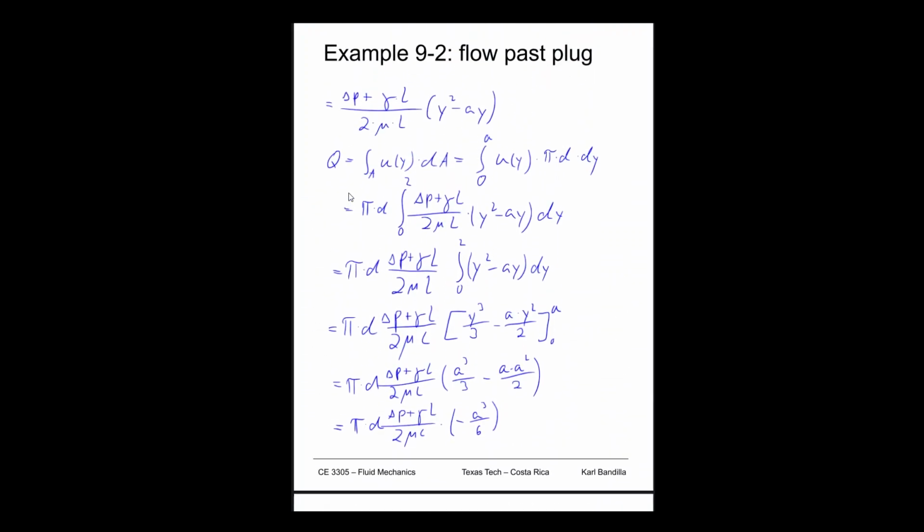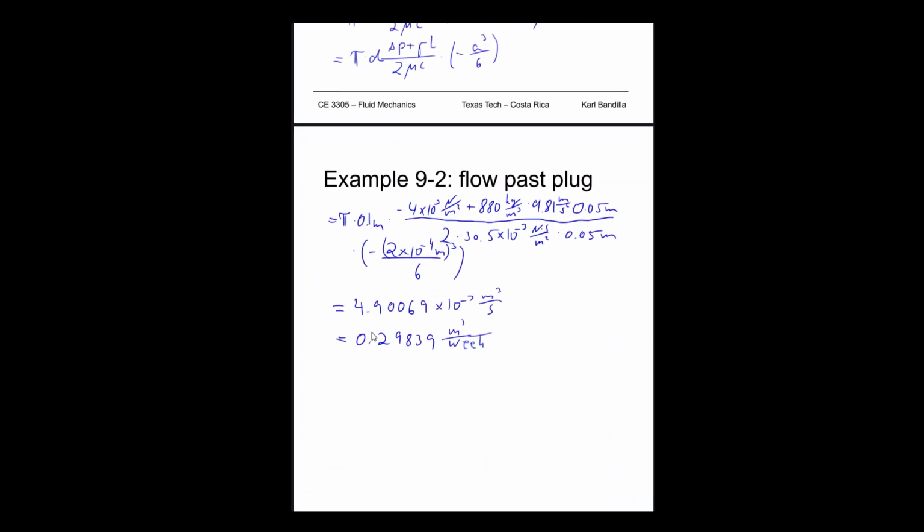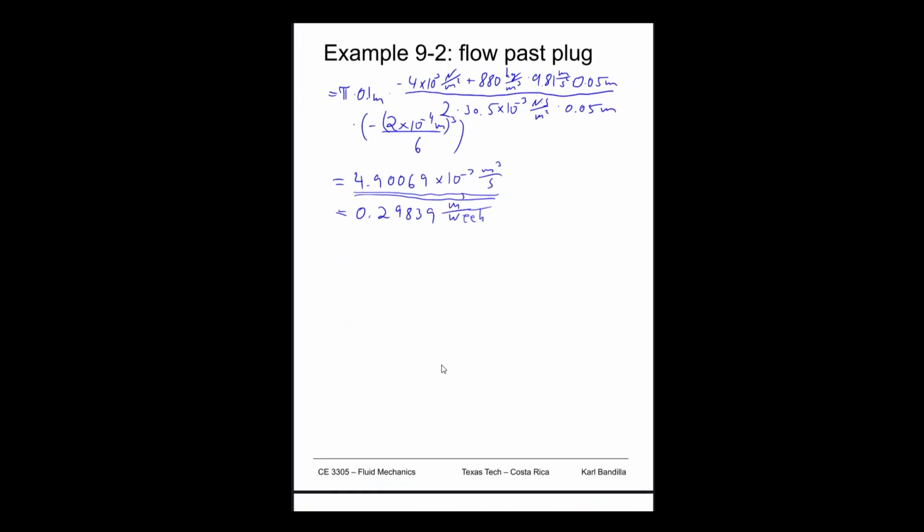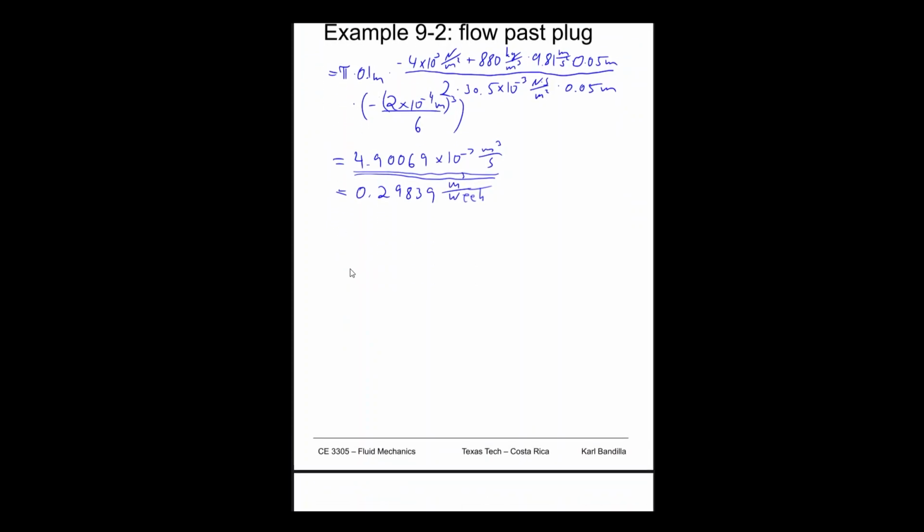And where do we have? Wrote it all the way at the top of the previous page. So Q is equal to, let's highlight this one, and then we can use the other one just to get ourselves an order of magnitude. Now, before we finish, we should check if the flow is actually laminar. Now that we have the flow rate, we can get the velocity. So we can say check if flow is laminar. So we'll start by getting the velocity.